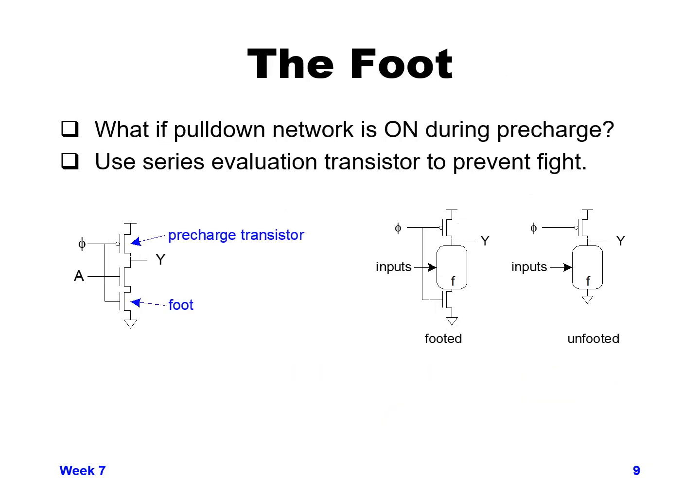Now in the previous slide, I mentioned that the input value needs to stay low when we're in pre-charge. Because if we had the input value high during pre-charge, then we would have contention between the pull-down network of our input and our clock, which is trying to pre-charge the device. So what happens if the pull-down network is on during pre-charge?